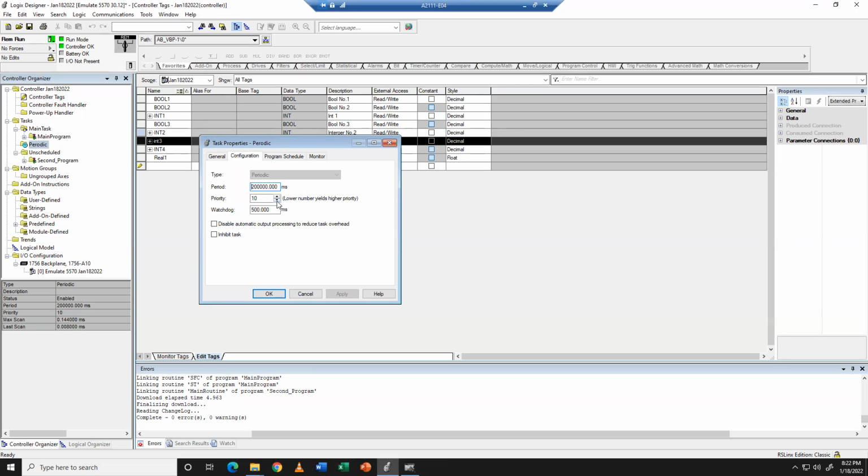priority, which means that if the processor starts to lag down, you can shift the priority for the entire cycle. I don't know the last time I actually had to do that with anything in my industry. If you have specific questions about that, I can look them up for you and work with you if you're having a processor watchdog a lot. If you're doing a lot of motion control, you do need to start watching your cycle times for safety, but you're also going to have safety features for motion, especially robots, welding, all of that stuff. I just don't have a lot of current experience with it, and I don't want to speak to something that there could be many firmware upgrades and advancements that I just haven't had time to look into.